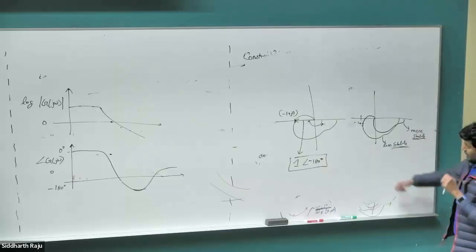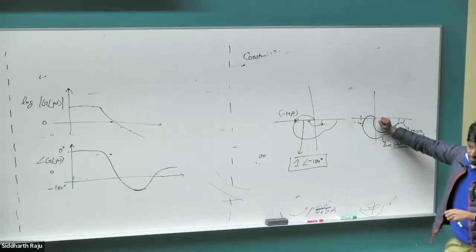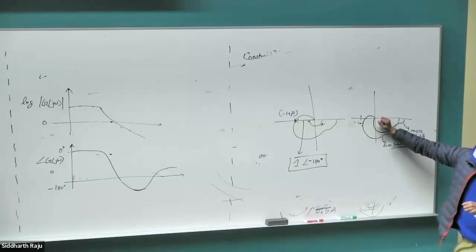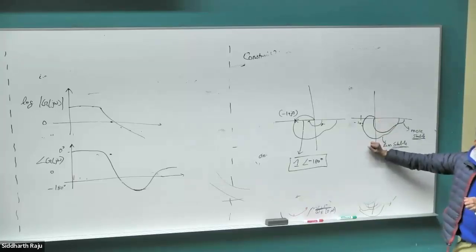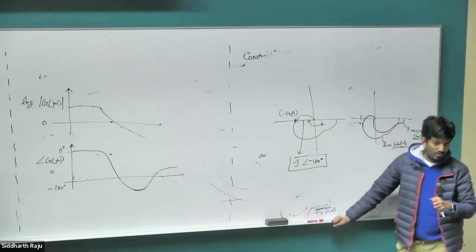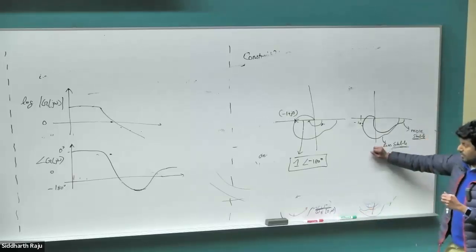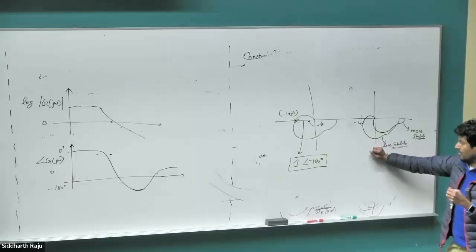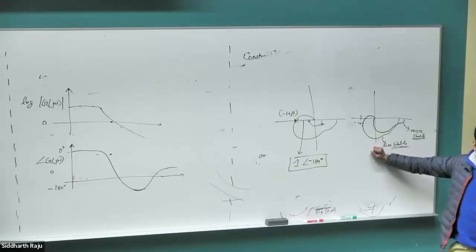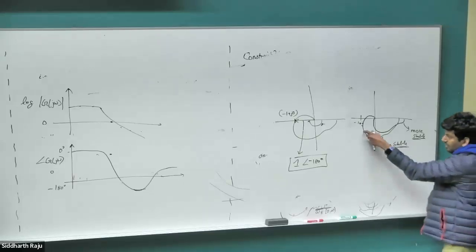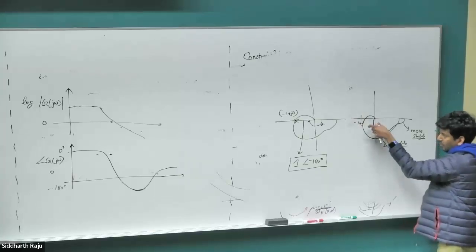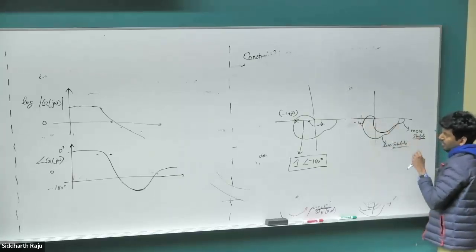Right? Why are we defining this as slightly less stable than this one? What could cause this to become unstable? More phase. More phase? Perfect. So the phase can come from multiple different ways. We also looked at one example where our measurement is delayed in some way. If our measurement is delayed, this gets pushed a little bit backwards. This curve also gets moved a little bit backwards.